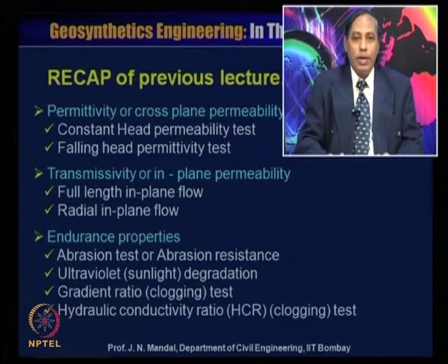Then transmissivity or in-plane permeability, that is under full length in-plane flow and radial in-plane flow. And next, endurance properties, that is abrasion test or abrasion resistance, ultraviolet or sunlight degradation, gradient ratio or clogging test, hydraulic conductivity ratio, HCR or clogging test.